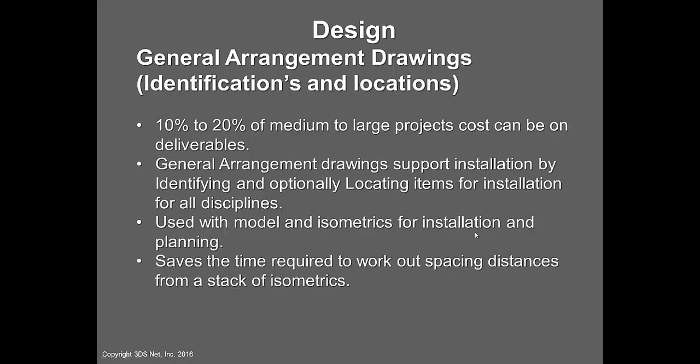The general arrangement drawings support the installation of the pipe or the equipment, identify everything, and locate them for all disciplines. Use this in addition to a model viewer and ISOs. It's not an either-or situation. It's an extremely good complement to a 3D model and a set of ISOs.